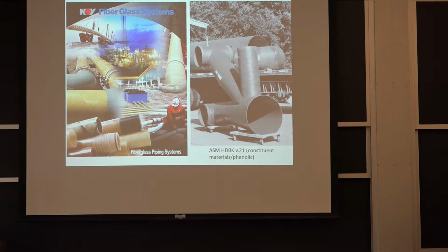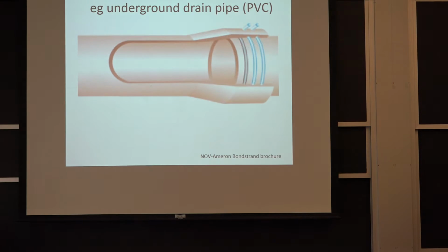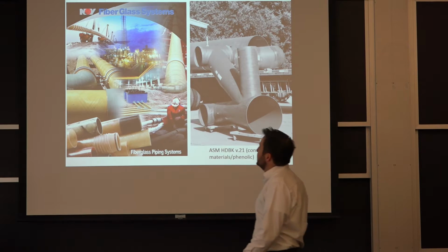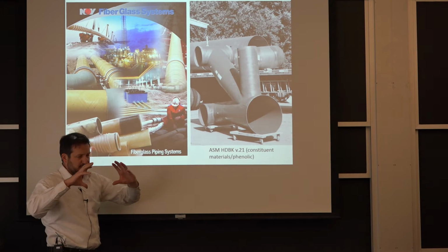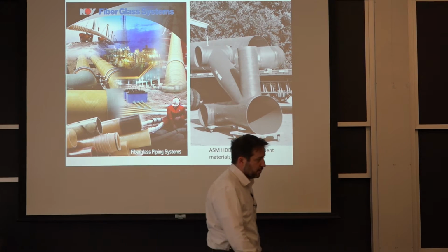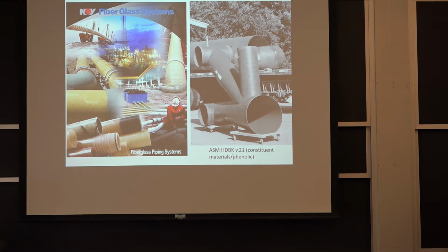One of the main issues here is joining again. Because if you have your reinforcement, that happens with bicycles and any kind of composites. It's very strong, but then how you take multiple pieces together becomes an issue. So this solution we just went through together with the O-ring is one that's used also for these composite pipes. You can have some special clamps. You see them here. So harness clamps that just take two sections and put them together, and a lot of O-rings. But you can see that it's a lot more involved than if I have two pieces of plastic that I essentially glue together, which is the way we do the sprinkler pipes.